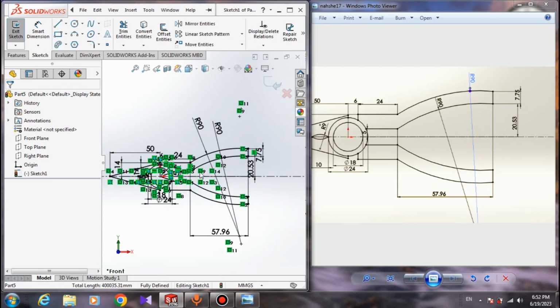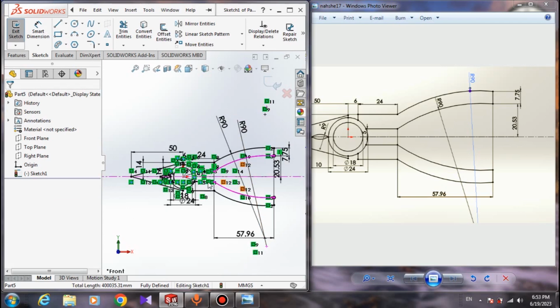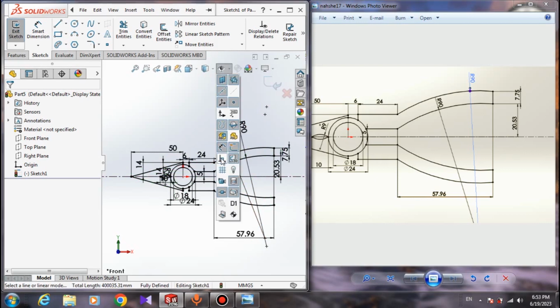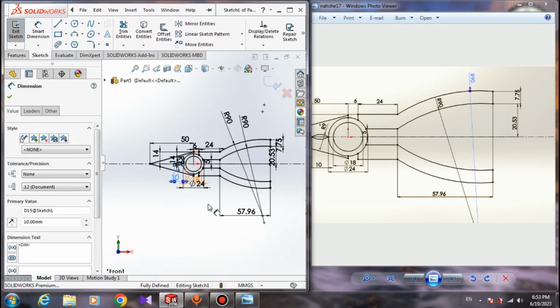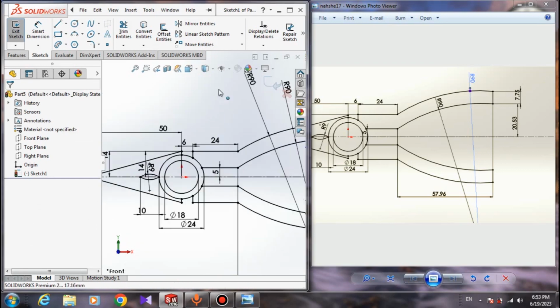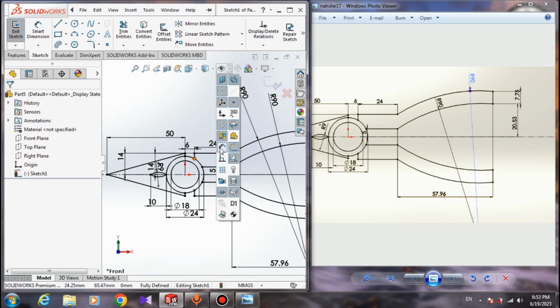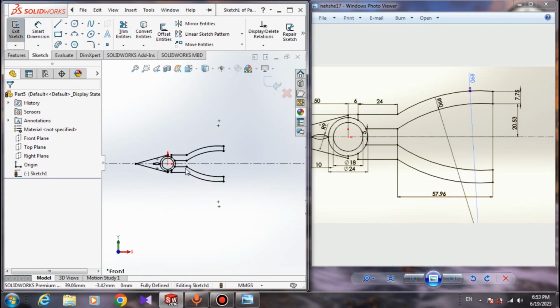It was a very useful session of SolidWorks. You can see it's a little bit hard to see our sketch. So here in hide and show items, turn off view sketch relations. The relations won't be shown. And if you want to see your sketch much better, you can come to hide and show items and turn off view sketch dimensions. Now it's much better.